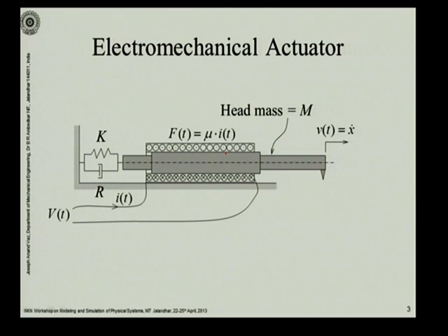It's also used in your magnetic discs. There are several applications for this kind of actuator. Here we have got a core which can move, it can slide through this winding. It's somewhat like a solenoid winding, and one can impose voltage, okay. So the voltage can be imposed across the coils of this winding, and the sense of winding has been provided using this cross and dot, okay.